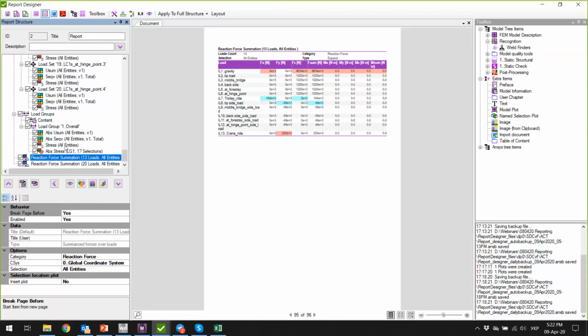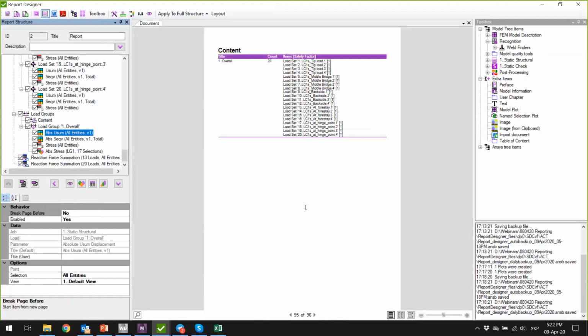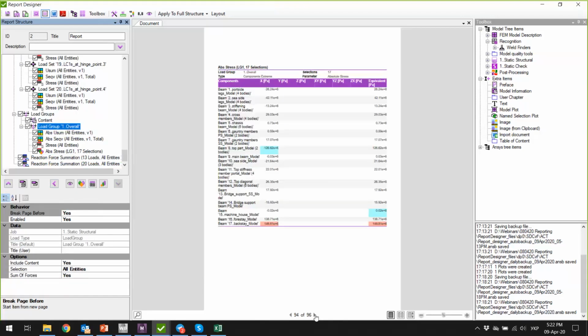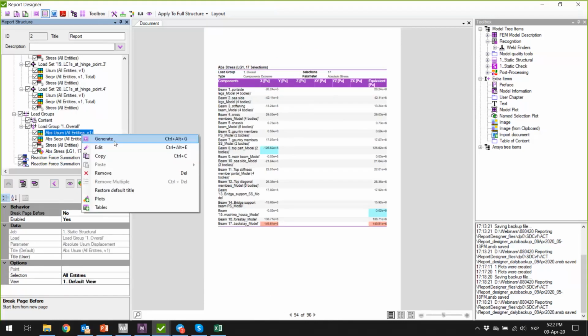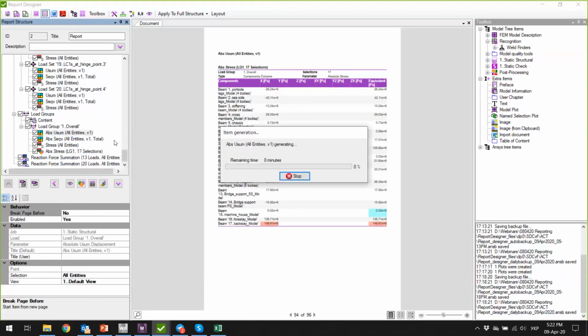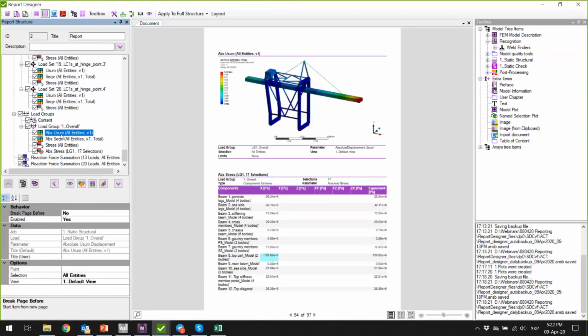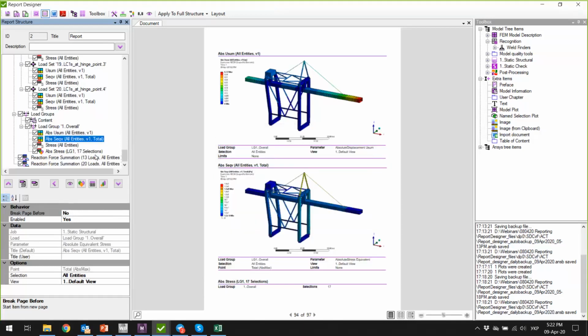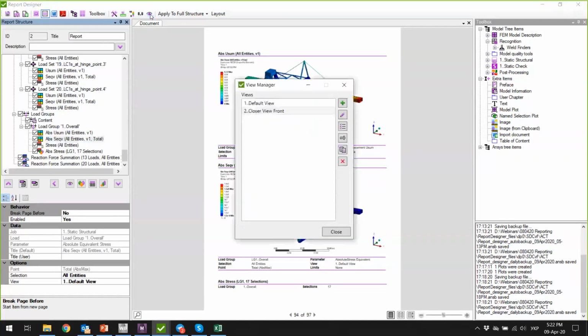And another thing I want to show you. We have this view on the complete structure, but we want to see the problem spot, which we have. Let's say it's going to be on displacement, the location with the highest stresses from a closer view, or only this location. So what do we have to do then? We go to views, and I have already created the view, but we can copy the default one.